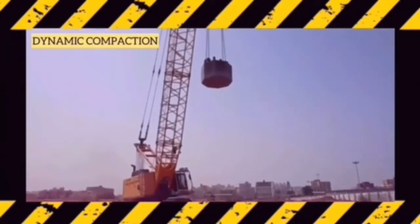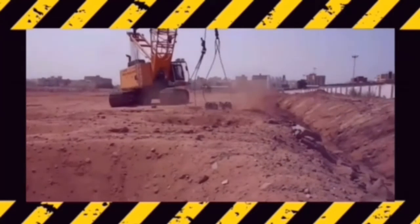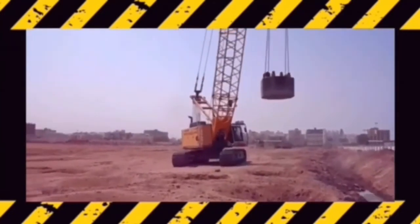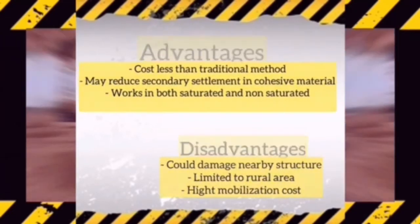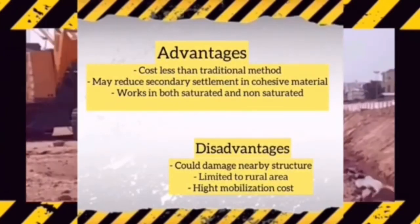The last method is dynamic compaction, or heavy tamping. This technique is mainly used for deep compaction and literally involves dropping a weight that is suspended from a crane onto the ground. The technique involves repeatedly dropping a large weight from a crane. Drop height typically varies from 10 meters to 40 meters, and this technique costs less than traditional methods, and it may reduce secondary settlement in cohesive materials. The disadvantages are that it could damage the structure and has a high mobilization cost.